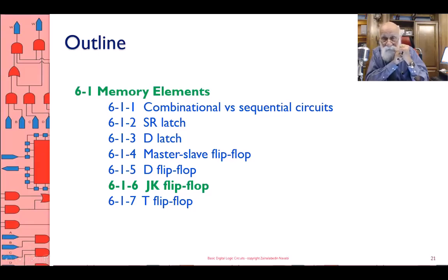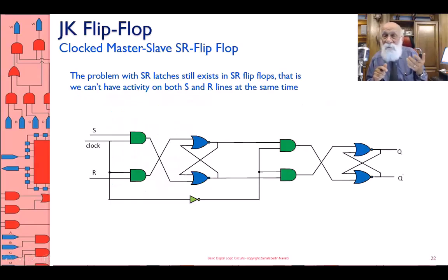But then there are times that you still want S and R, meaning that you want something to be set, something to be reset. Okay, so remember what we did before. We said, well, the set and reset doesn't look like a memory storage element. So let's put an inverter between the set and reset, and then make it a D flip flop. I'm gonna remove the inverter now and say, well, no, S and R is not a bad idea sometimes. So this is an S and R flip flop. Okay, so it is not transparent.